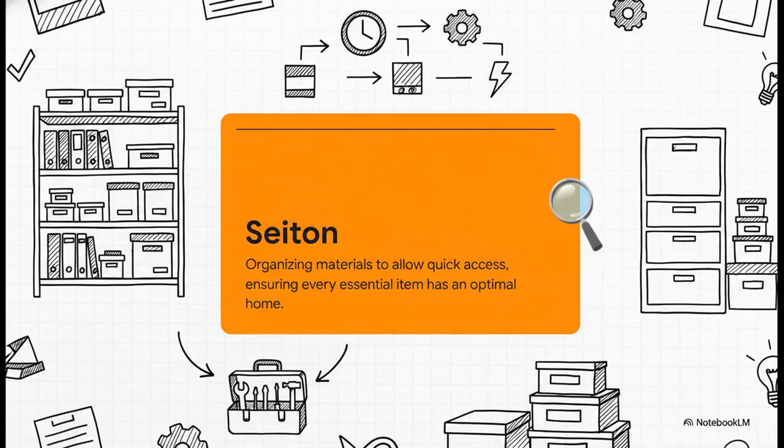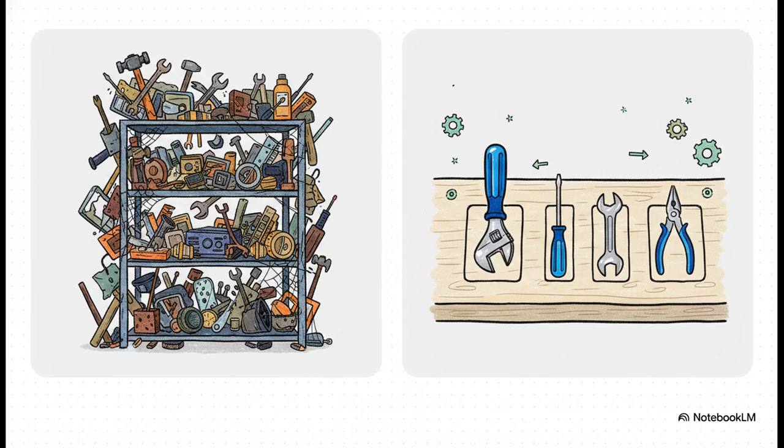But notice that key word in there, essential materials. That word essential brings up a really common, very dangerous trap, which perfectly illustrates why the sequence matters so much in 5S. You simply cannot jump straight to set in order. Think about the stark difference between these two concepts. First, we have organized waste. This happens when you attempt to organize a space before you have rigorously decluttered it using the first S, sort, or seiri. If you're building beautiful, custom storage bins for tools you never actually use, you haven't improved your process, right? You've just created organized waste.